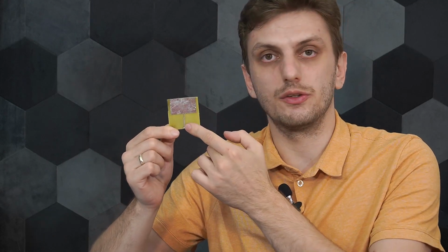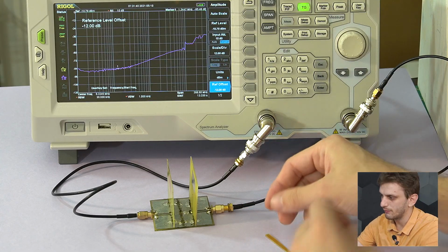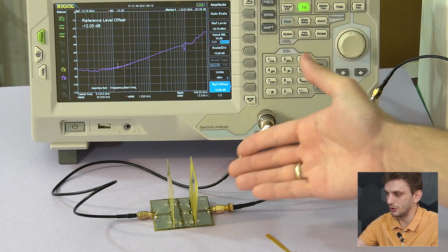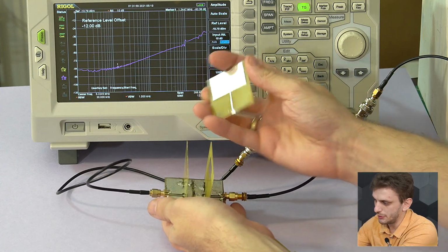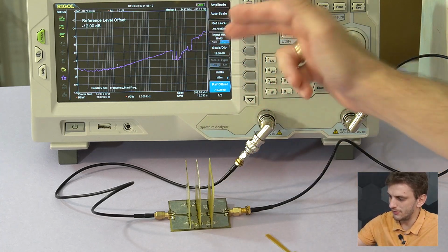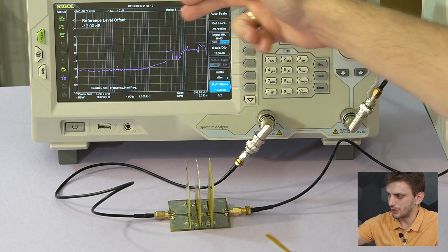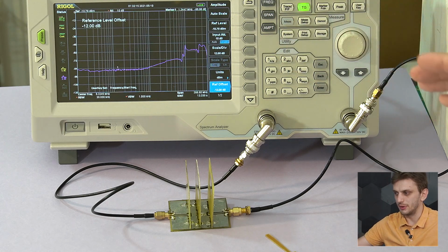So what I have here is a much larger plate now connected to ground, and if we insert this thing in between the plates, so first of all I remove the initial wire, we should see our coupling increase. So now there's no shielding, nothing in between, it's worse. And now if I insert this large plate, we can already see that there's a definitive drop in coupling. I have about 12 decibels per division here, and we see a very clear reduction in coupling.